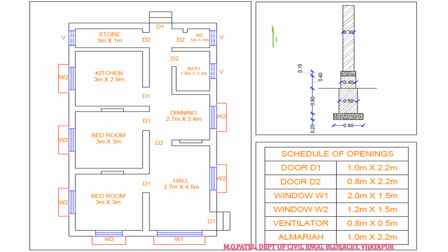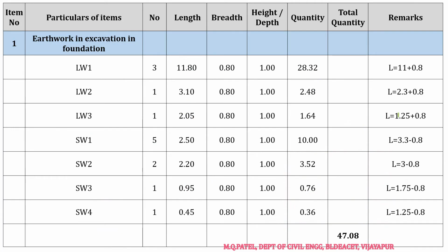You see, 1 meter is the clear distance, correct? Here they have given it. At the top, this wall thickness is 0.3 meters, so we have to take half. Half of 0.3 is 0.15, correct? Then next, this is a 200 mm thick wall, so half means 0.1, right? So 1 plus 0.25, therefore it is 1.25 meters. So the center to center length is 1.25.